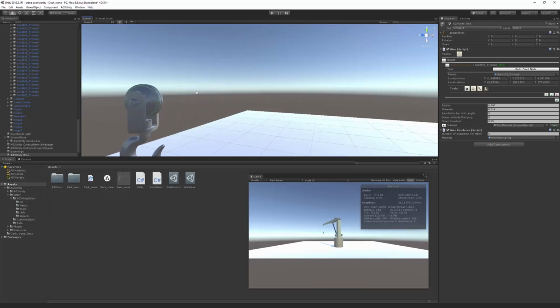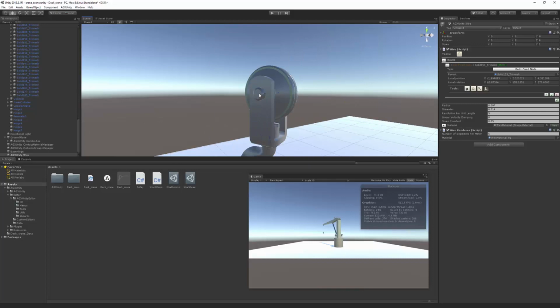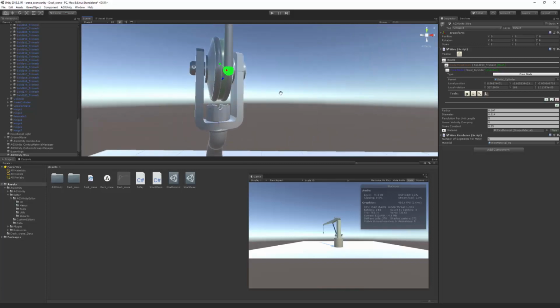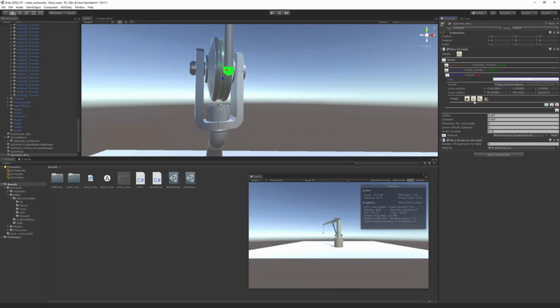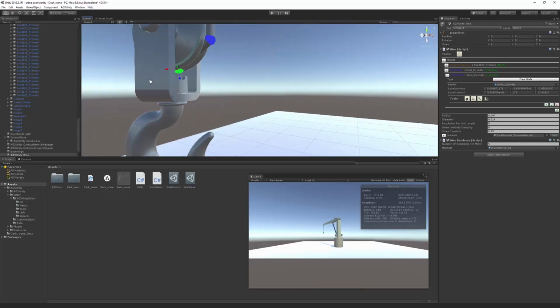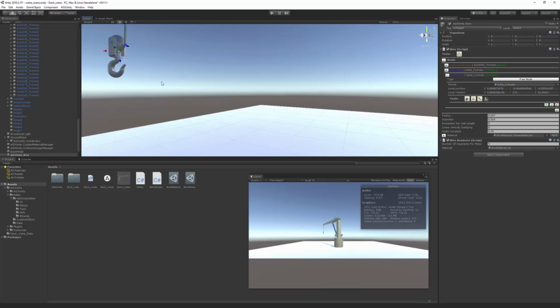The next node we're going to create is on the sheave, on the hook sheave, and it will be a free node. And a free node is something that will not be rigidly attached to a body. It will move in free space. It will be translated to contact nodes if needed. So we also need to make sure that we have some separation so that we don't model the wire inside of geometries, because that can result in a bad result. So we continue creating these nodes around the sheave so that it goes freely around and comes up on the other side, also with a free node.